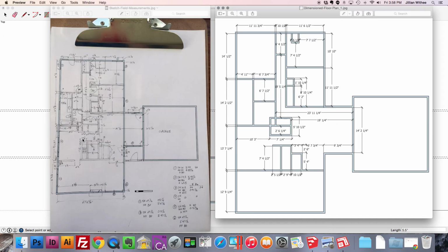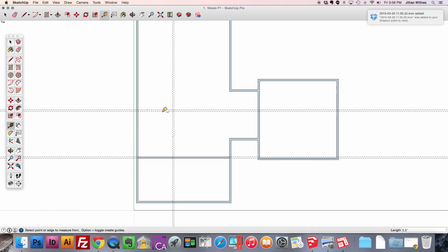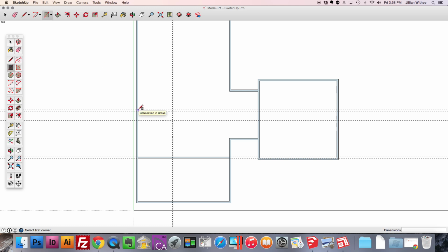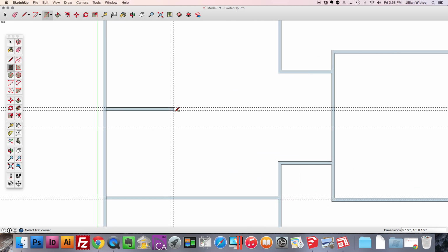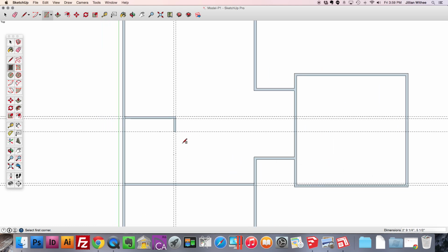And if I go back now, this is actually, I think, 33.25 inches from this wall to the face of this wall. So I can go back in 33.25 inches. Oops, 0.25 inches. And this is how I use guidelines to rough them in. So now I can use my rectangle tool, same as we did last time, come over here, draw that wall, and then draw this wall.